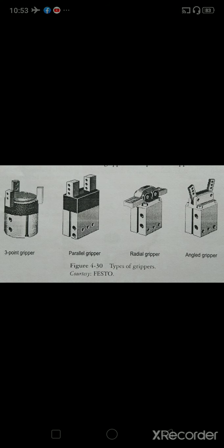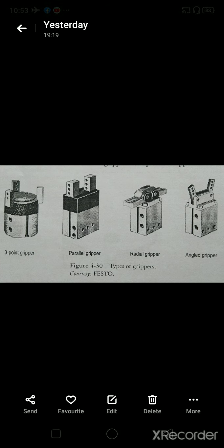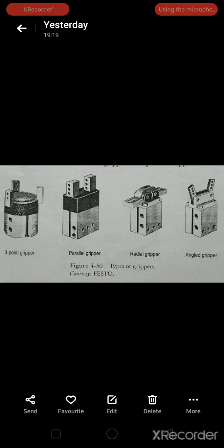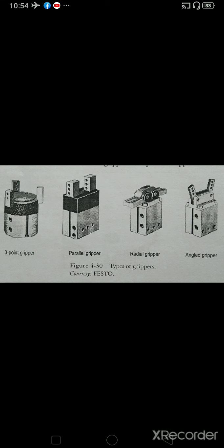A finger-like gripper is made of a double-acting pneumatic drive with fingers attached to the cylinder piston through a rack and pinion or lever mechanism. The piston movement makes the fingers open or close. The finger shape is to be tailored or manufactured as much as possible to the shape and type of surface of the workpiece in order to achieve a large effective area.